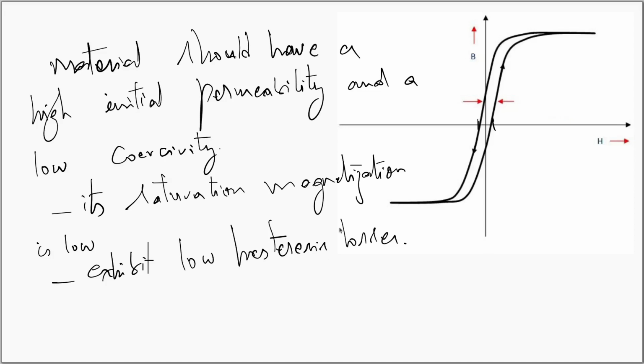These materials have very small area under the hysteresis loop. Since the area of the hysteresis loop represents the energy lost as heat during a cycle of magnetization, the smaller the area, the lower are the power losses, and the greater the possibility of using the material at higher frequencies. A low value of coercivity corresponds to the easy movement of the domains.